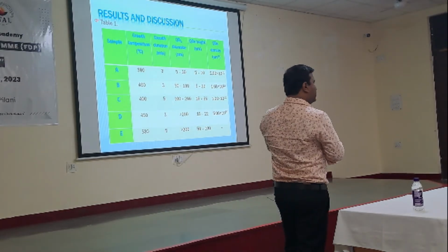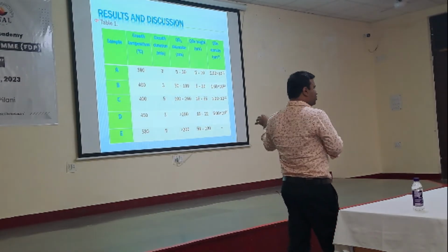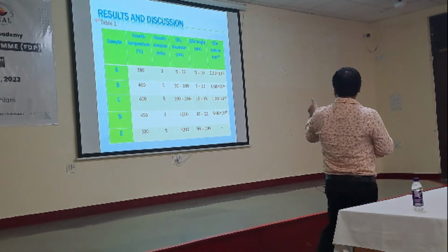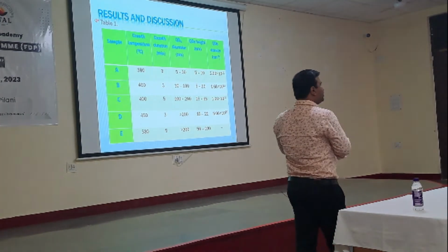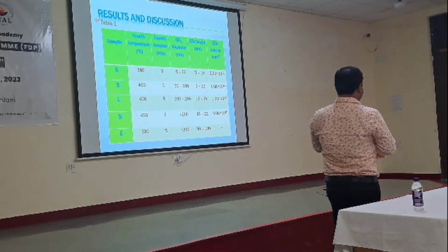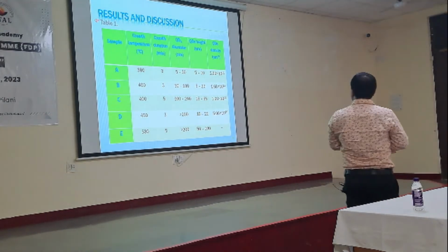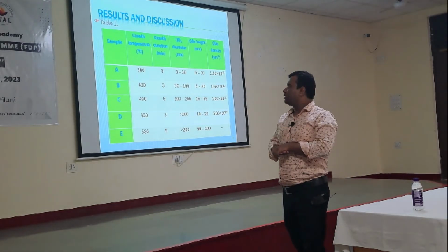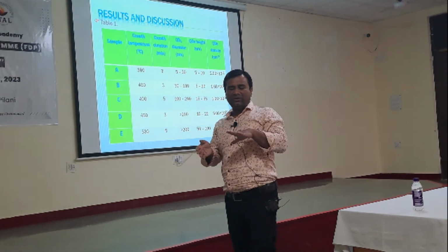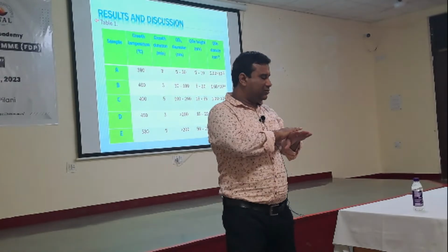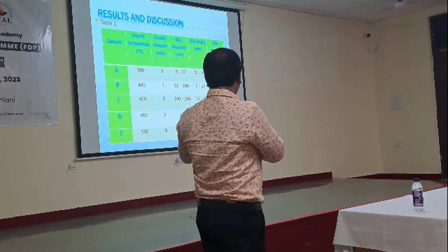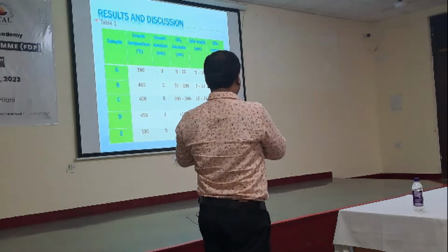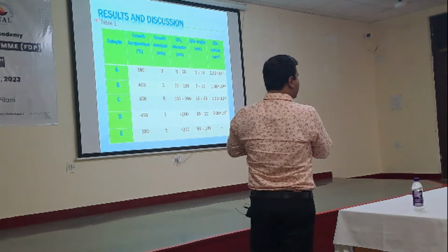Because if you increase the temperature, the precursor molecules I use, trimethyl indium and arsine, the adatoms become more mobile, and that facilitates very high thermodynamic action. So rather than formation of quantum dots, a thin film will actually be deposited, and nano islands will be formed instead of quantum dots.